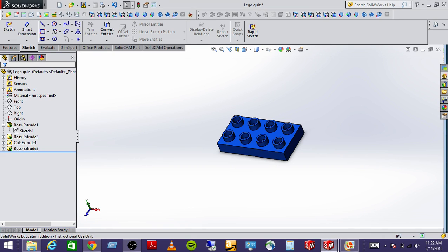But in my CAD model, if I ever want to go back and use the original potentiometer that he wanted, all I have to do is suppress these components and unsuppress the other ones, and bam, I got a more versatile model. It's right there. I didn't delete it, I don't have to redraw it. So it's pretty useful to use this suppression feature. So I wanted to show you that.